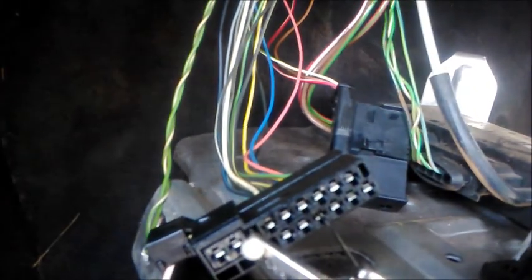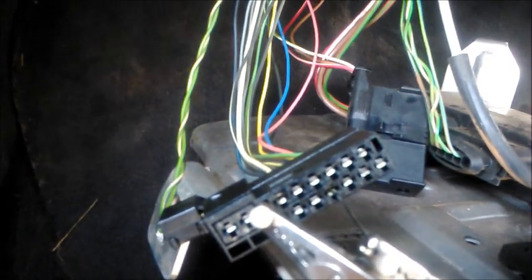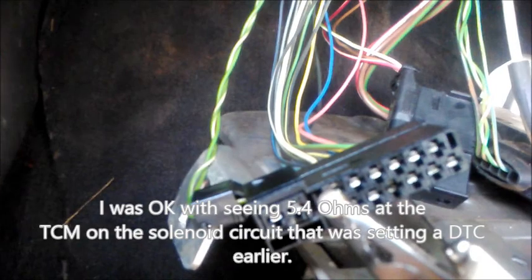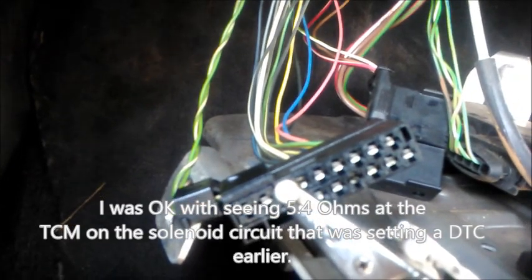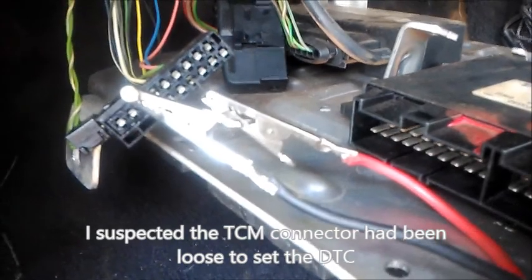If you look at the connector, you see it is all full of transmission oil. So I think I'm okay with that. The spec is 4.5, I'm getting 5.3 even with all that oil on the connection, which introduces a bit of resistance. I think that solenoid is fine. There is just a loose connection somewhere. The solenoid that is giving the fault code is fine.